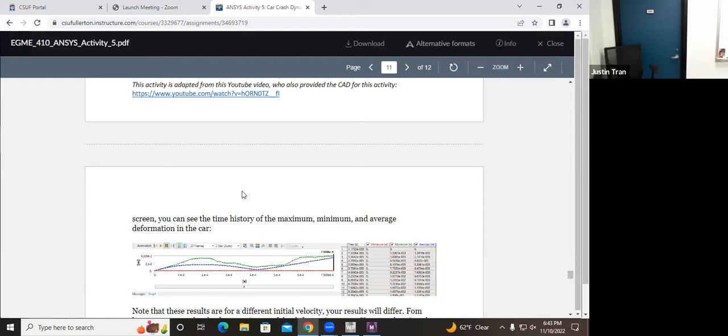Backslash is basically the same thing as matrix inversion. To get the deformation, you invert this matrix and multiply that by the vector, but backslash is a shortcut to do it. Then to get the reaction forces, you take your deformation result and multiply this matrix by it, and that's going to give you F1, F2.